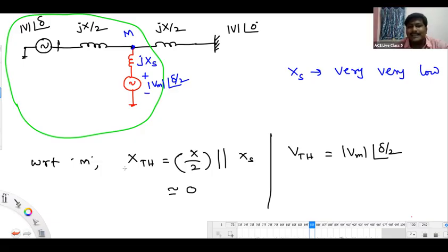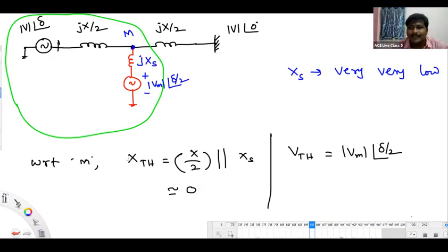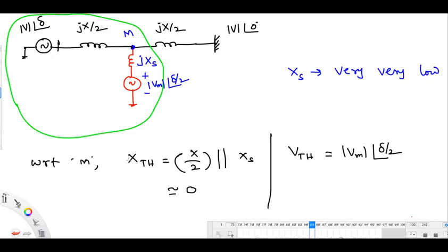You say Pmax is high, in that sense you simply say stability is high. If we go beyond x equal to root 3, can we say the system will be stable or unstable? That you can't say, right? X more than root 3 or x less than root 3 is not a condition to say the system is stable. This is only for the Pmax.